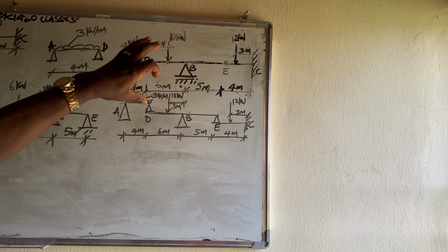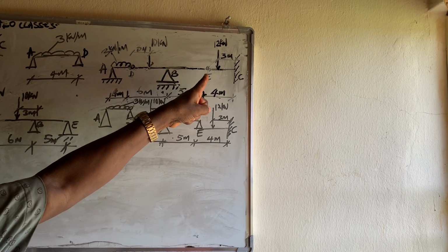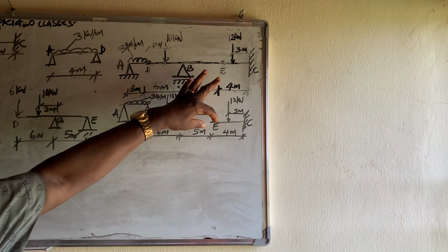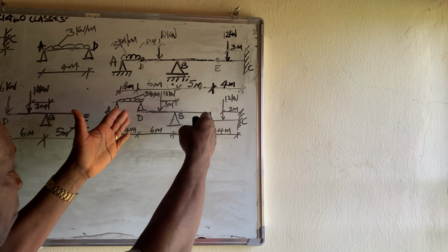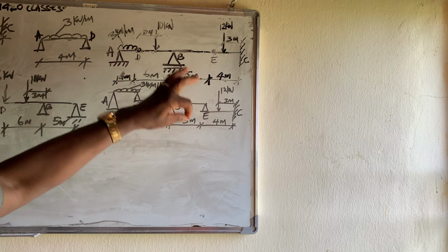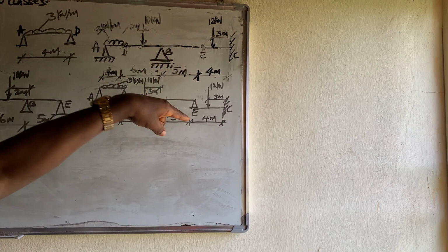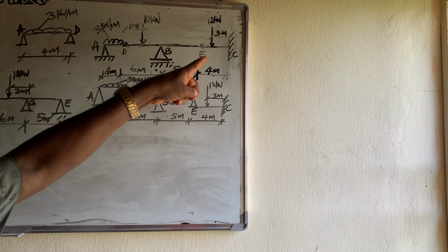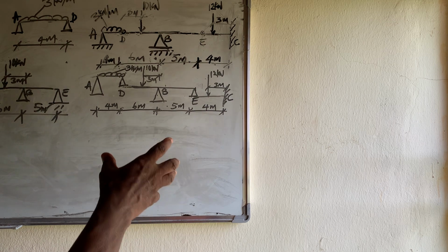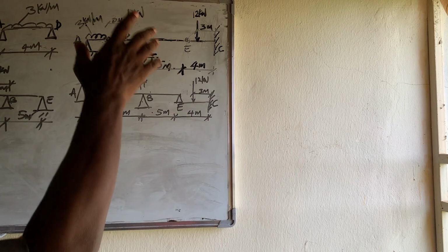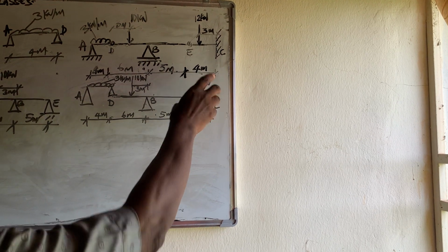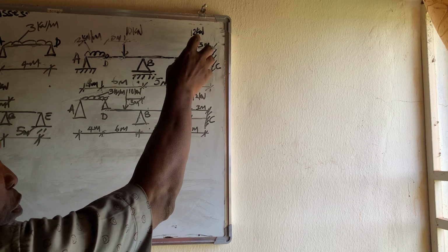So we rested it on DBE. And when we rested it at DBE, we cut the next hinge at point E. So we cut it at that point to get another part of the beam, which is DBE. And we had to rest it on the most stable part of the beam, which is EC, because point C has 3 reactions that could sustain a beam, whether it is pushed horizontally or vertically, or even if it's rotated. All those resisting reactions are in C. So that's the most stable part of the beam.